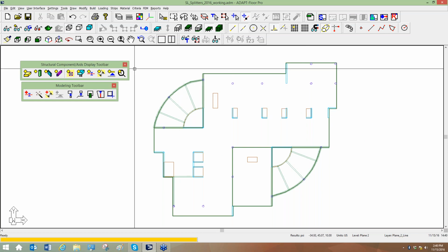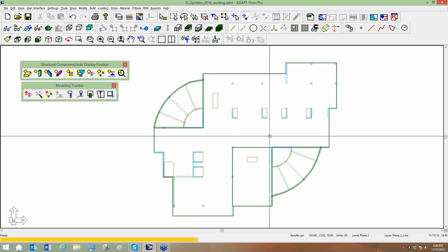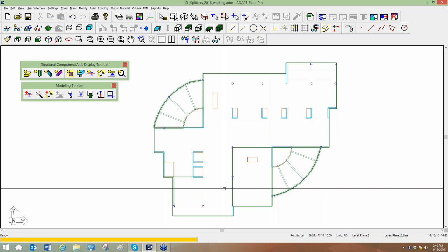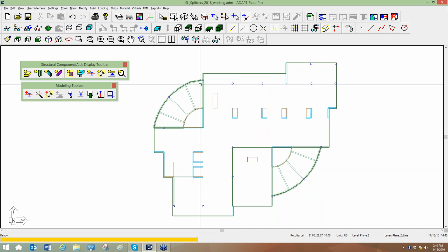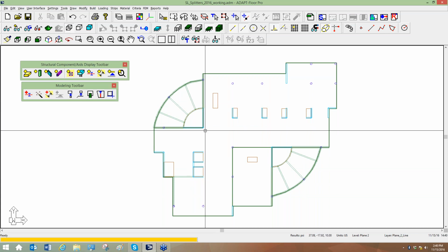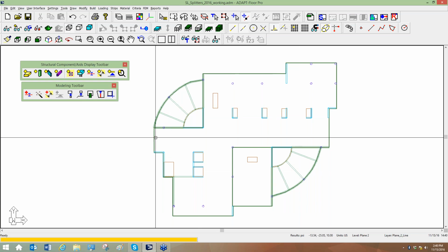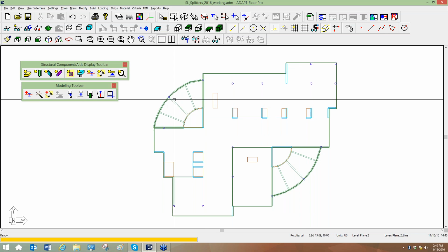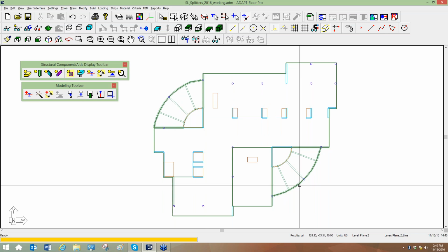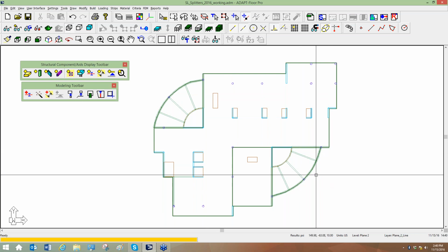Now, we're going to dissect this slab into three zones. We're going to do the X direction first. If we have time, we'll do the Y direction, but X should give us a good idea of what we're after. And we're going to create strips for this rectilinear slab, and then we want to create separate strips for these regions that have this radius shape or these arcs out on the edge with the beams.